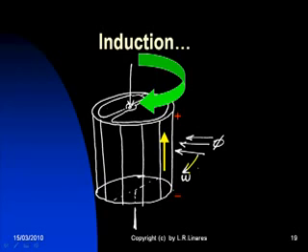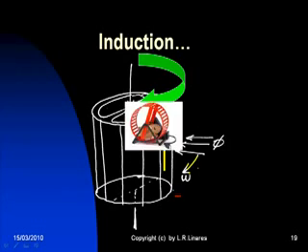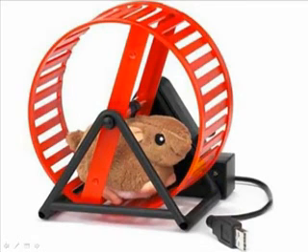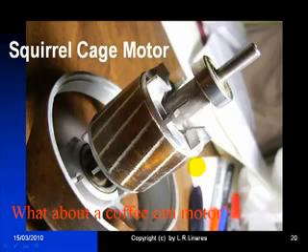If you imagine that rotor rotated 90 degrees, it looks indeed like a squirrel cage. That's why that type of rotor is nicknamed a squirrel cage rotor. And the whole motor around that is called a squirrel cage induction motor. Now in this case we have about 16 of those wires or bars, slightly skewed to be sure to avoid some other problem we haven't mentioned. You see those wires and the rings that connect them at the top and at the bottom.